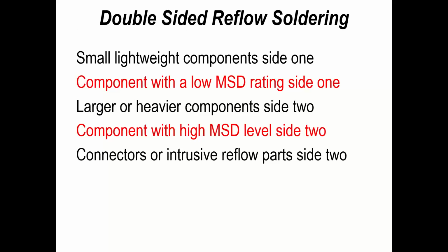So let's talk about double-sided. I alluded to the fact that with double-sided soldering, you've got to think about the second side. Some companies do, some companies don't. But please remember that a component absorbs moisture. If you are running the boards through side one, and then within the next few hours doing side two, it shouldn't really be an issue. But remember that the reflow soldering operation, because of the small time and temperature we're talking about, is not really going to take out much moisture if it's present, but it shouldn't be present to start off with. But if you hold the components for a long period of time, or if you're doing some other operation to the boards and components, then you might have to consider moisture.